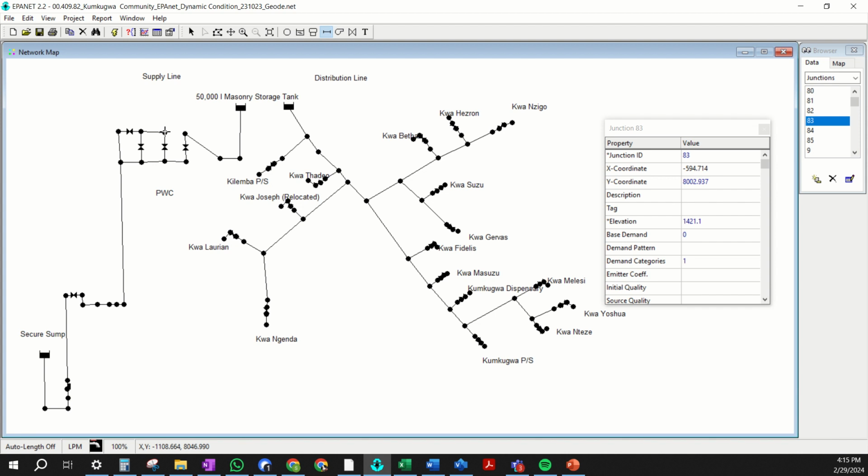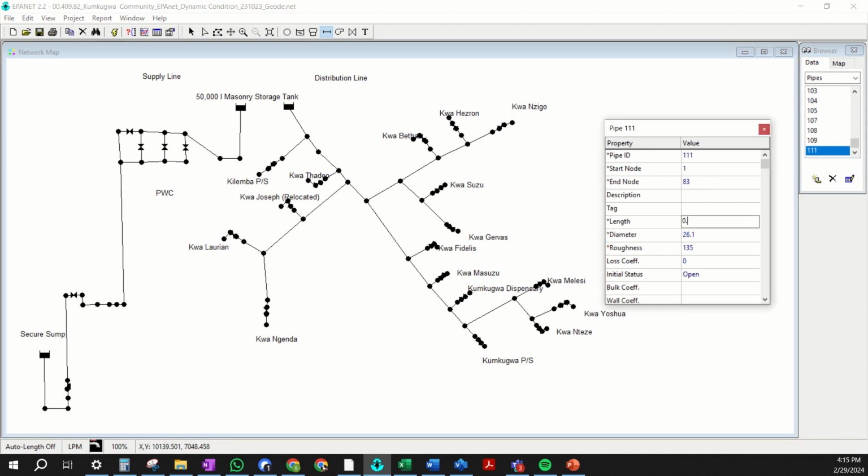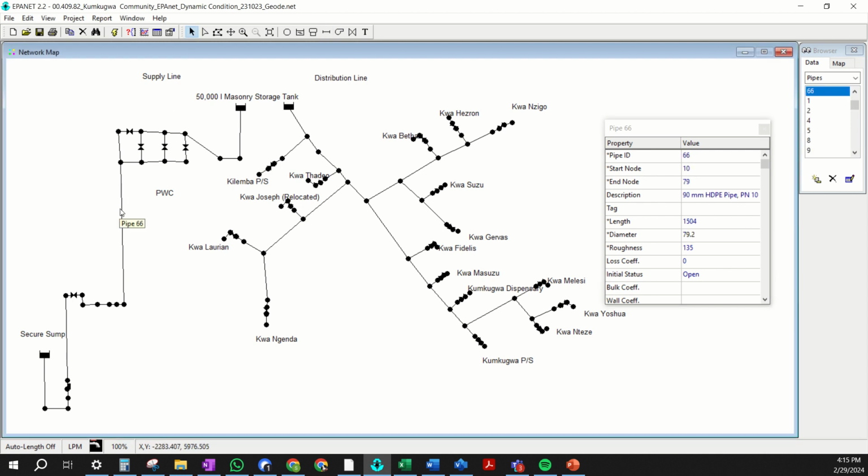I need one more pipeline to connect this last chlorinator. And the pipes in between the chlorinators can be very short. I'm going to put 0.5 meters in between each chlorinator. The diameter should be equal to the diameter of your pipeline. So this is a 3-inch pipeline, so I would use either 2.5 or 3-inch piping inside the treatment house.